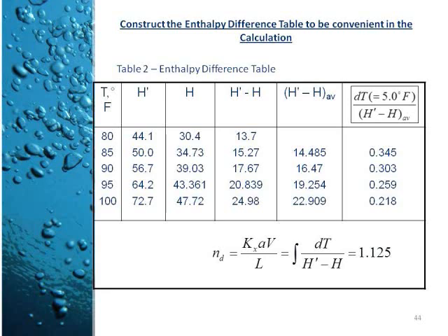From that equation, values such as the saturation humidity, the liquid loading to gas loading ratio, as well as the hot water temperature are constant. Cold water temperature varies from 80 to 100 degrees Fahrenheit.